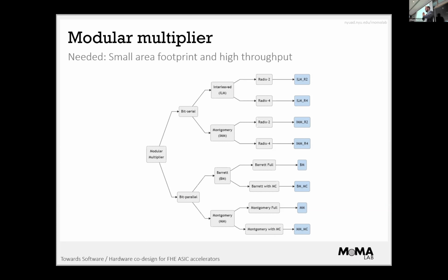So these are modular multipliers, right? The modulus in the generic form of multiplier can be any size, any form. However, if you restrict the form of the modulus to be, for example, having a lot of zeros, you can do that because you pick the moduli yourself, right? When you create your encryption and you do your RNS, you pick the moduli yourself. So you can pick the moduli to be of a specific form.